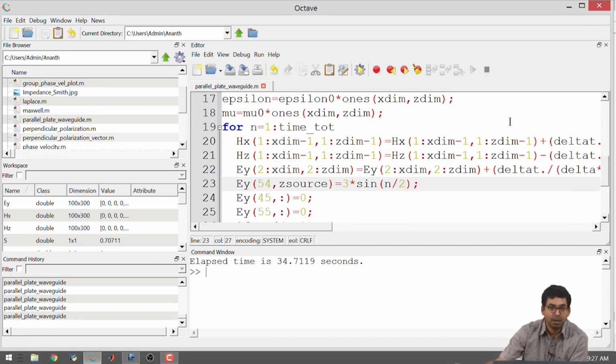You have more than one mode, and they are beating with each other at different instants. Now you saw that towards the end it was single mode, but if you run it for more time, that pattern will change. That is why it is easier for us to operate a waveguide under single mode condition, so that you do not have this confusion as to what kind of pattern will be present at what instant of time in what space.